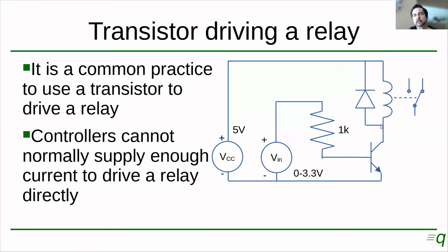If we were trying to make a boost converter, this is something we would want to take advantage of, but this is not a boost converter. So we just want to provide a path for the current to discharge. And that is what this diode does. So when the transistor turns off, this node here goes positive to a high voltage, and that's going to turn on a path here for the current through the coil to dissipate through the diode.